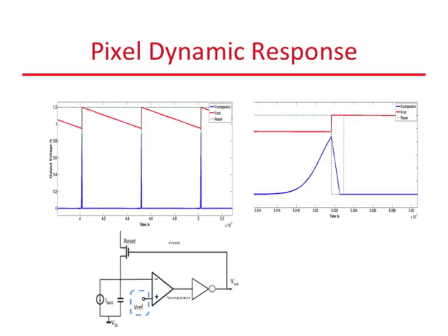Subsequent illumination of the diode repeats the above cycle. At the output node, pixel output, a pulse edge is observed. As a result of this operation, the circuit converts a quantum of incident light into a pulse train. The intensity of the incident light is encoded in the frequency of the pulse train, with larger frequency corresponding to higher illumination intensity and vice versa.